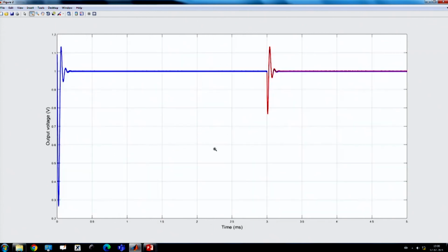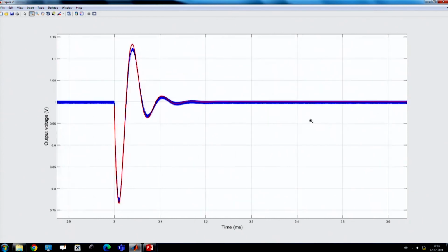So, as we push higher and higher gain, the model matching using first order approximation is not the right solution. Once you go for a type 3 compensator, you will get perfect matching even at 1/10 of the switching frequency. Here, because we want to achieve first order response, that is why it is not matching correctly.